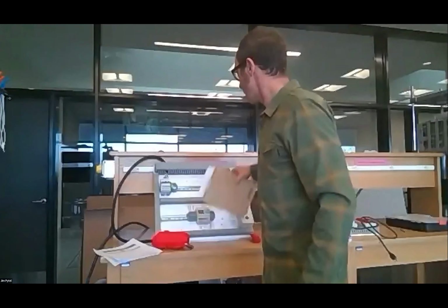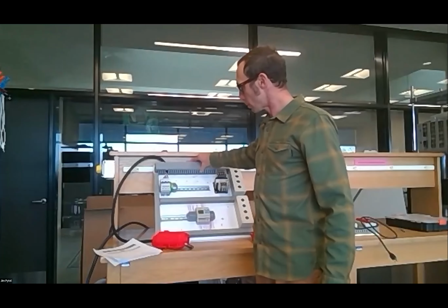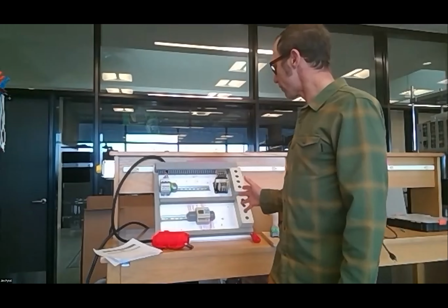And last but not least, the actual motor controls trainer itself. All it is, it's a metal backing with a bunch of wire ducting on it. The circuit breaker and control transformer remain mounted on it. The programmable logic controller also remains mounted on it. And like I said earlier about the motor, I don't like having students wire up the programmable logic controller because it has very, very small screws. So I've taken all those inputs to the outside to terminal blocks, so they interface with a 15-cent terminal block as opposed to an $80 programmable logic controller. That is all I've got right there.